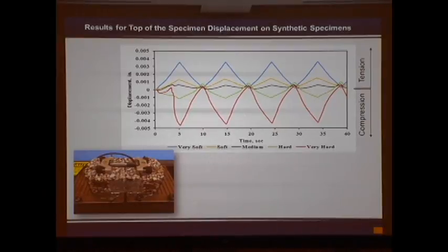So we felt there might be some issues not only with how this was bonded to the plate, but also with the load frame. And we found some of those issues too, where we were getting some compliance in the machine. The mixes were so stiff, and you know what our mixes were looking like, especially the ones going 1 or 2, 5 cycles. They're very stiff, and all of a sudden they're bending this frame when you start to try to pull them apart. So that was some of the issues we were seeing.